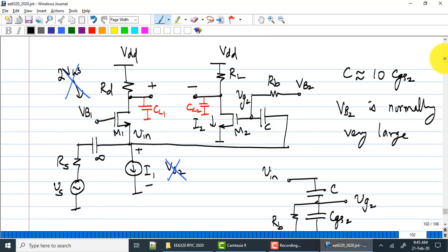Yeah, of course. I just wrote the dominant caps. How do you AC couple? What does that mean? This has two outputs. I add two capacitances in series and then connect to the next circuit. Can you name those other capacitors?